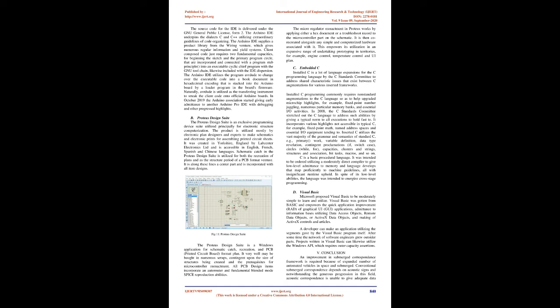The microcontroller simulation in Proteus works by applying either a hex file or a debug file to the microcontroller part on the schematic. It is then co-simulated along with any analog and digital electronics connected to it. This enables its use in a broad range of project prototyping in areas such as motor control, temperature control, and UI design.